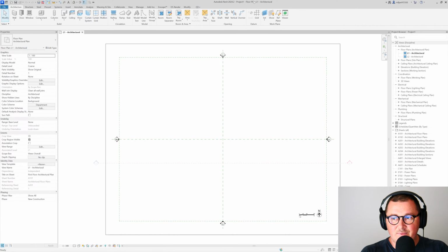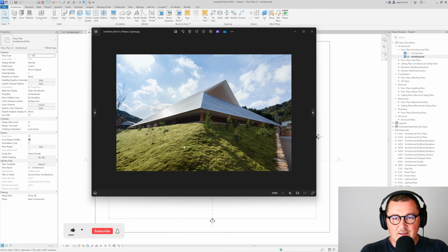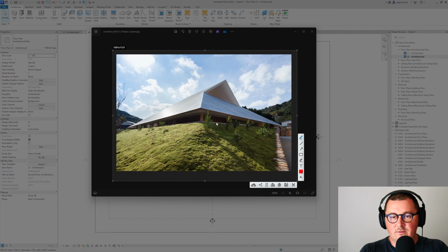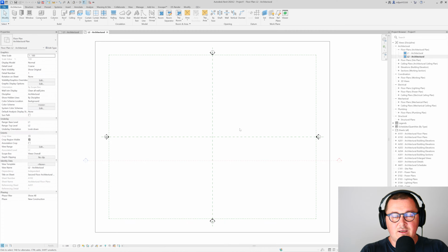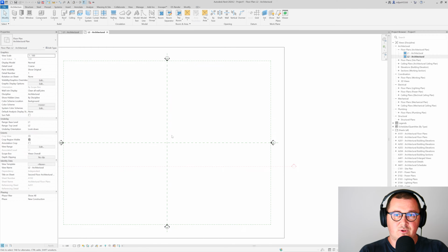So in Revit, I will just open the second level, so that's the place where I'm going to model the roofs. And let's say that this is going to be the first roof which I'm going to model. So you see that we have the roof which goes this way, and then we have this. So as I said at the beginning, you should draw its shape as if you are doing the projection from the top, like, let's say, drawing the lines in AutoCAD.